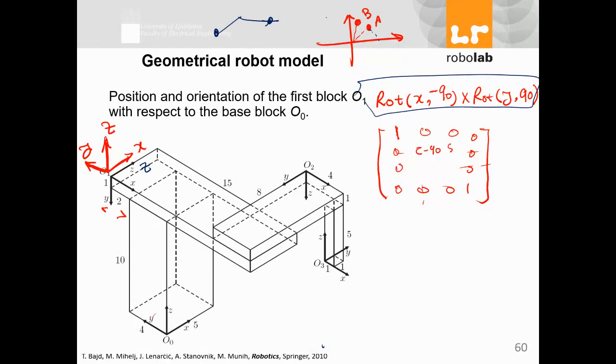In terms of a robot, it will be different. But mathematically, just looking at free movement, or a translation from one point to another point, I can imagine there might be an infinite number of sequences that end up at the same transformation. But having said that, the homogeneous matrix you get should be the same. Even if you do it through 10 different rotations, you should get the same answer.